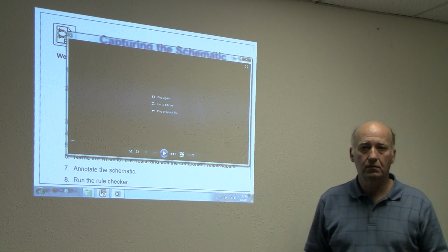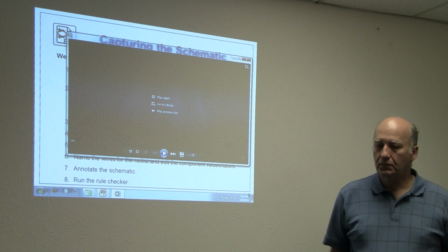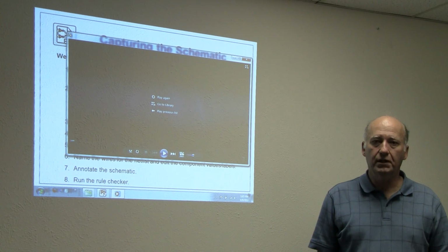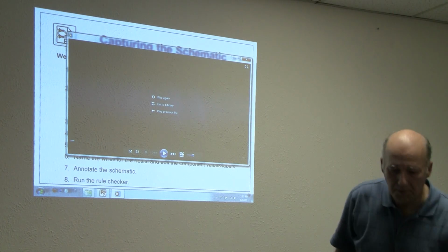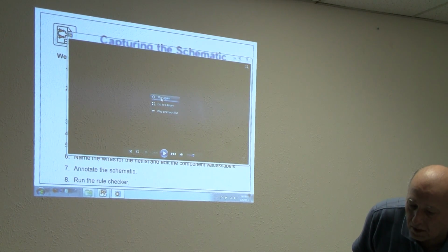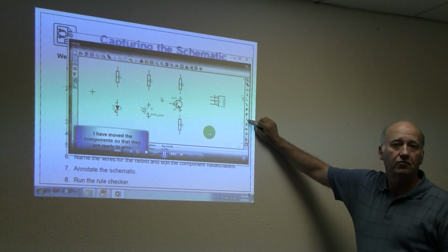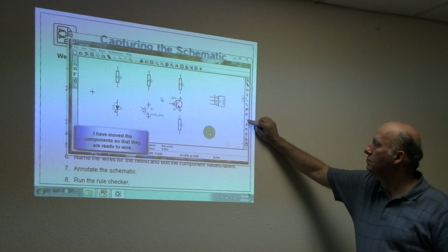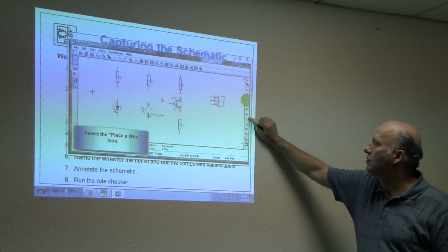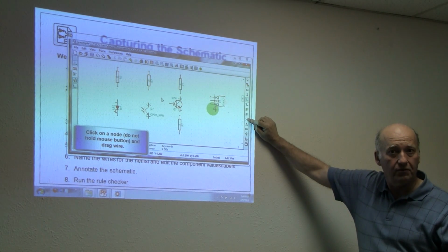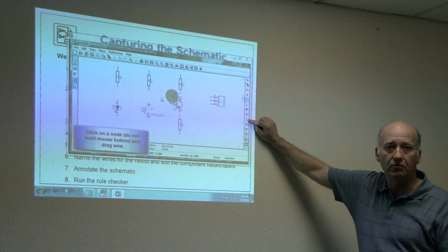Yes, sir. I was just going to ask, if you have a chip and you're only using some of the pins on that chip, is it going to complain about the unused pin? Okay. There it is on the sidebar. Okay, let me play that again. We're not going to play the whole thing, but I just want to show you this. This is the don't use button. So if you had a pin that you didn't really want to use, a lot of times in a microprocessor, you may not have all the pins being used. You would click this on each of the pins that you don't have.